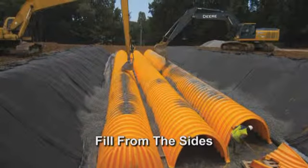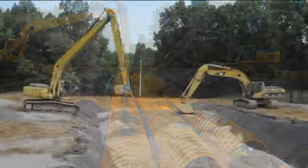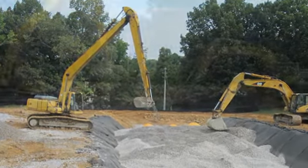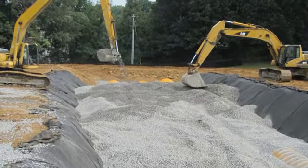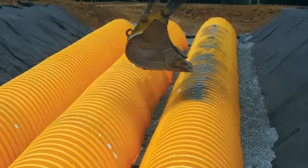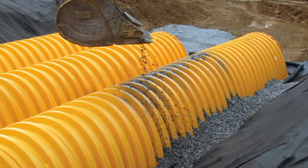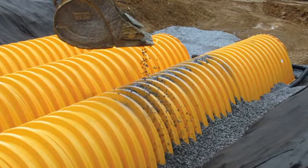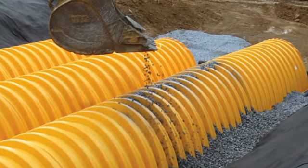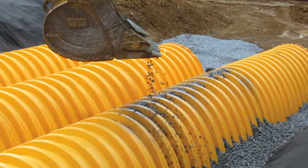With method 3, the embedment stone is placed by equipment positioned outside of the excavation, usually a long boom hoe. The bed can be backfilled either after the entire chamber system has been assembled or as the chamber rows are being assembled. When placing stone by reaching across the rows, the operator must be careful to place stone on the crown to ensure even distribution on both sides of the chamber. In accordance with these three backfilling methods, never is it acceptable to place equipment on the bed.